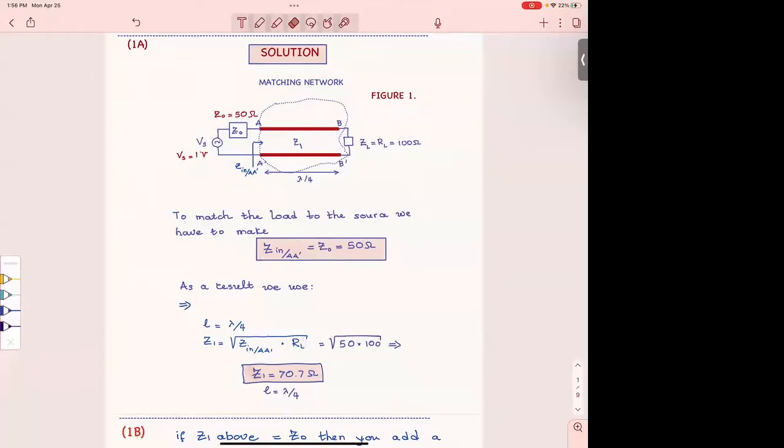If I give you a frequency, then from that frequency, you can calculate lambda. And I told you to remember that 1 gigahertz is 30 centimeters. And then you can scale up and down, all right? 10 gigahertz, 3 centimeters. 100 megahertz, 300 centimeters. So that's how it goes.